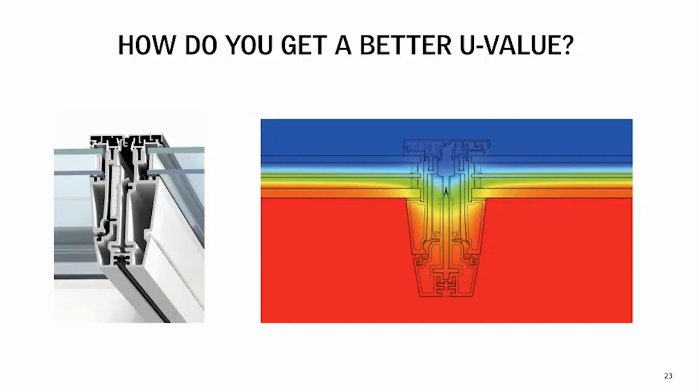The thermal diagram on the right, you'll notice that it's warm on the bottom. This is a cross section of a skylight, two skylights actually butting up against each other, so you can see the frame between them. And it's demonstrating that if you have a well insulated frame, you should be able to keep that frame, the inside surface, warm. And if that surface is warm, that means you're not losing as much energy through that skylight in what would be a cold situation outside. So you want this cross section, this thermal image, to be as warm looking as possible because that'll be a warmer skylight.